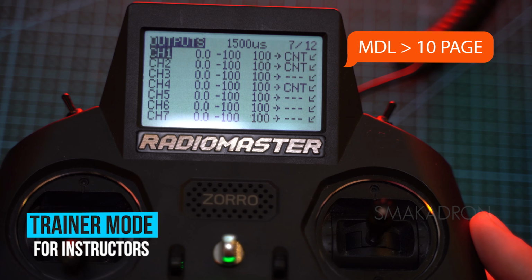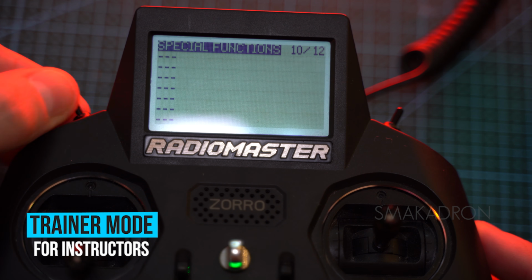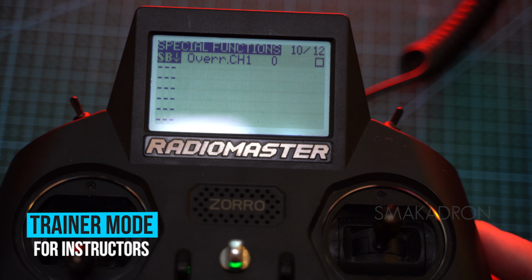Navigate to page 10, titled Special Functions. Select any free switch. For me, it's SB, and let's have it be the down position. In the down position, the student will control the drone. When I flip the switch to the up position, control fully transfers to the instructor.